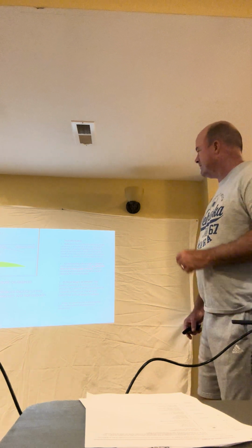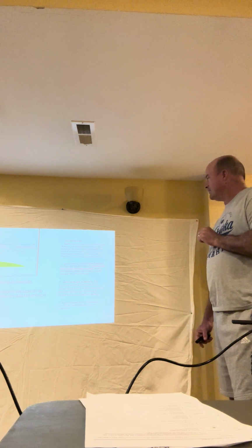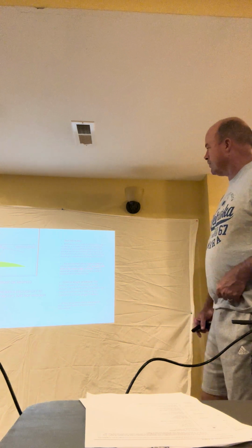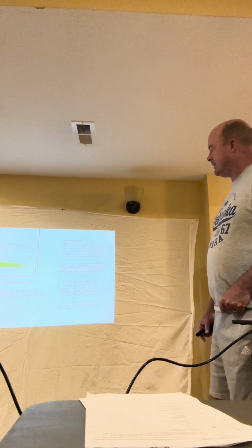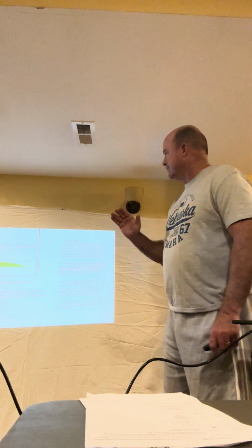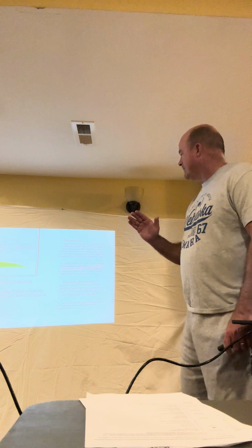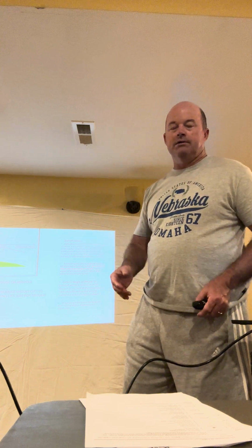As an airfoil increases its angle of attack, the coefficient of lift is increased, resulting in greater lift being produced. The point at which the reduction in lift occurs as a result of reduction of smooth airflow over the wing is called the critical angle of attack. So the critical angle of attack is right before it's going to stall, right? As soon as that airflow coming over the wing separates, you don't have any lift. Like the whole flying thing's over. You're basically like a car in the sky. So you're not flying anymore.